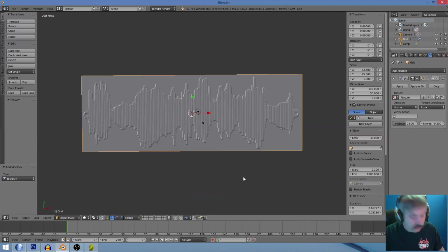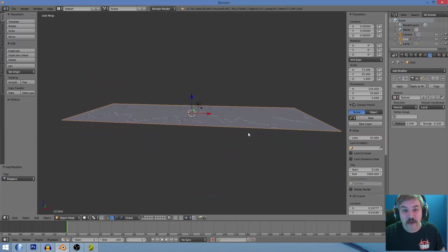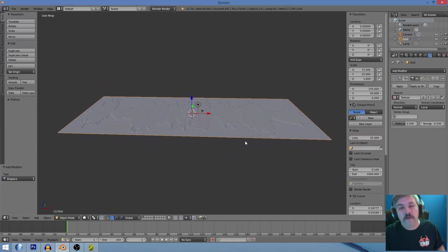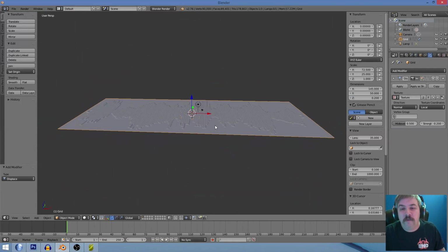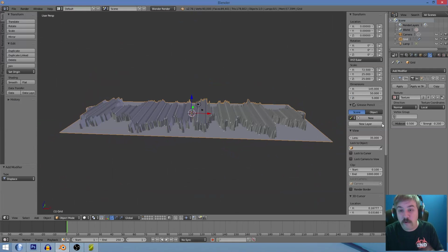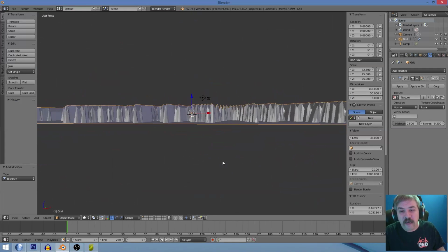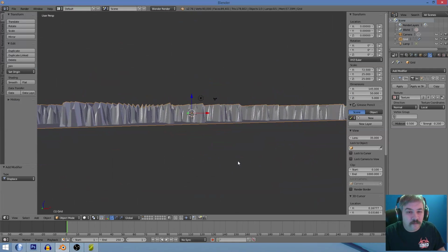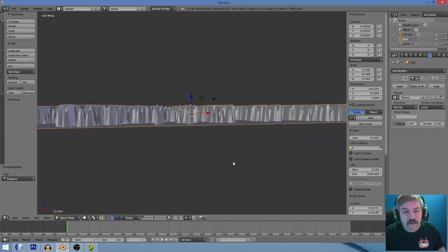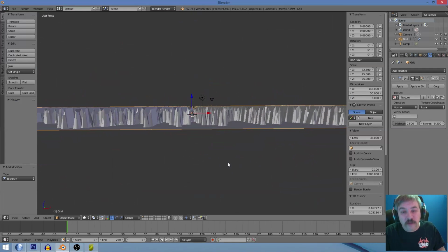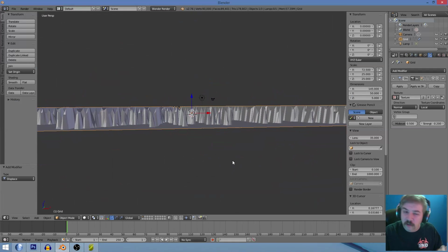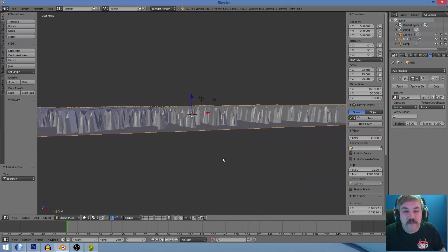If we go down here and rotate it down, we have no height whatsoever. If you were doing one of those litho photos in 3D, you'd be around this area. But we want something a little bit higher, so I'm going to go 5. If I look across the object here, I can see where the valleys are and how low they go. I do like that we're at a lower resolution, so instead of being actual valleys, they are tapered, and that's going to give some strength to the object as well.